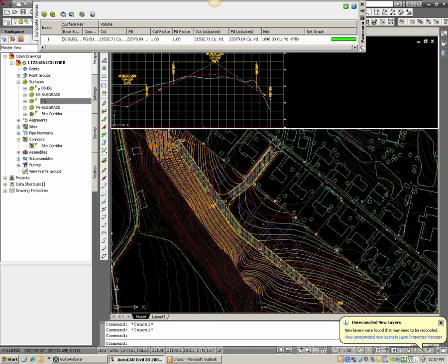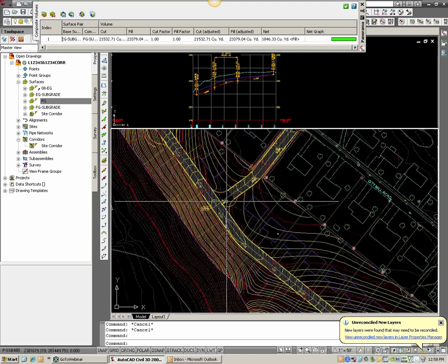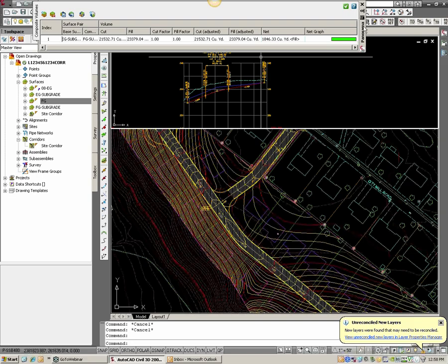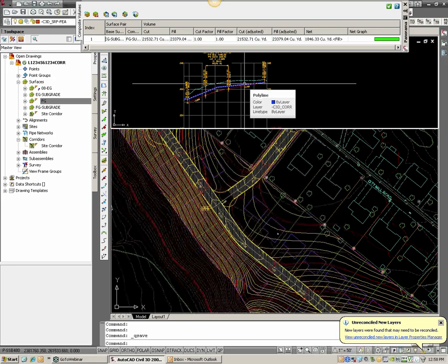Now, since I made that adjustment, you still need to keep things lined up for your roads coming into it here as well. A trick there is to also pull a profile from that corridor surface. So let's do that, and we'll leave with that here. And the point is, this is where your time is spent on residential grading, getting these road profiles set. So the fastest way you can do that is where you're going to save the most amount of time.